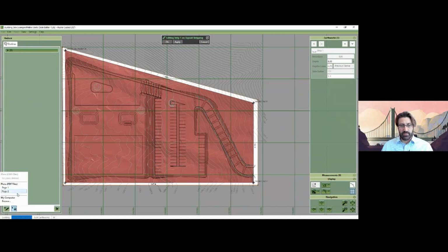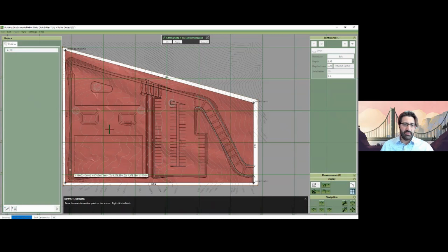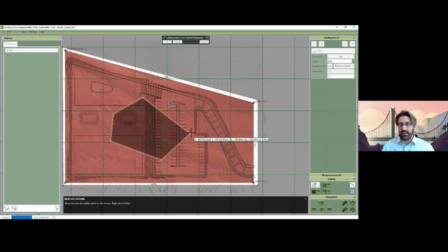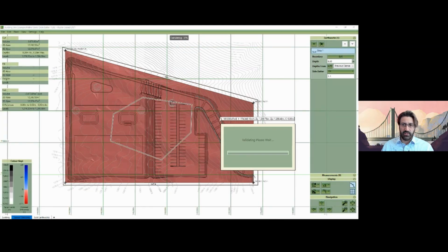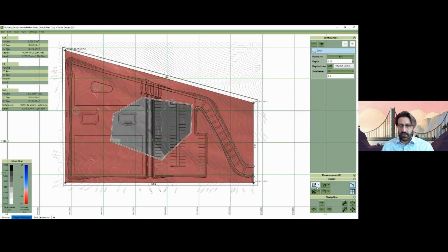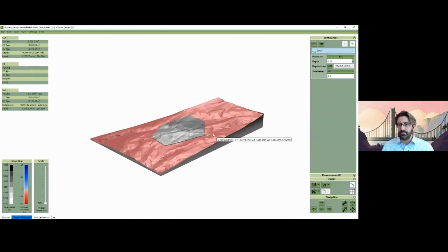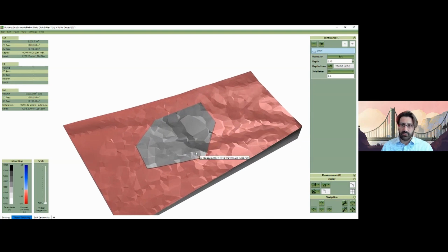We can even import them from CAD. And the beauty of this is that the feature surface supports punch out, so you could do an outline within an outline to specify a kind of negative area of your surface that you're modeling. Now we can do that in all the other elements, like a strip. So I'm going to do it here in a strip. And I've just punched out a hole. It's much easier than the other workarounds that we had.